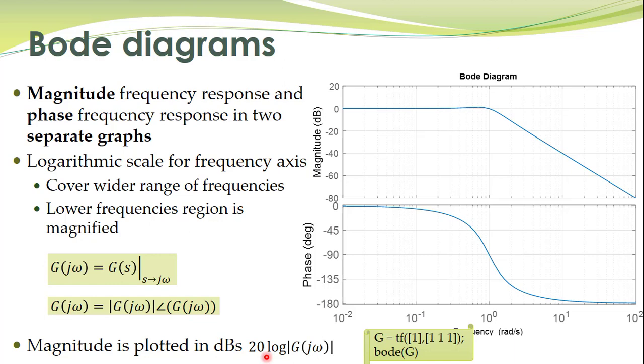You can also utilize MATLAB to obtain the Bode diagrams. You already know how to enter the transfer function of the system into MATLAB, and once you have the transfer function, you can use the command bode to get the Bode diagram for that particular system. Many times you will not have MATLAB readily available with you, so you should also know how to sketch the Bode diagrams by hand very easily.